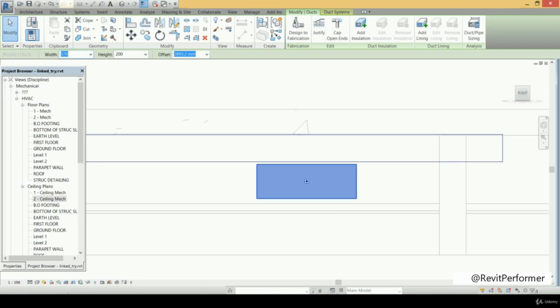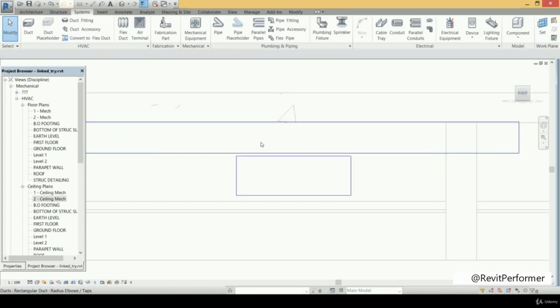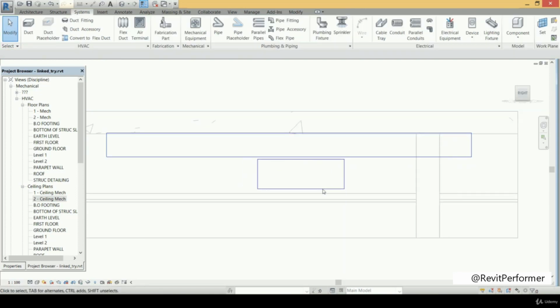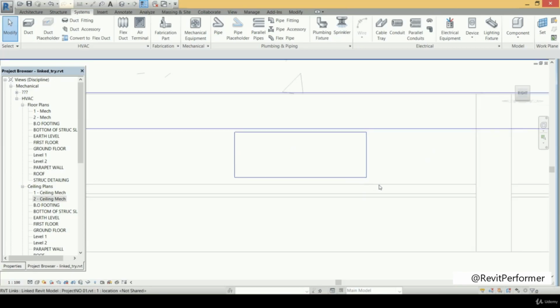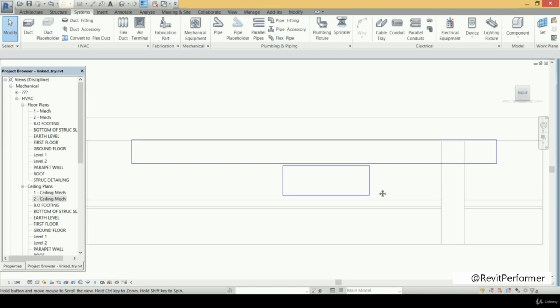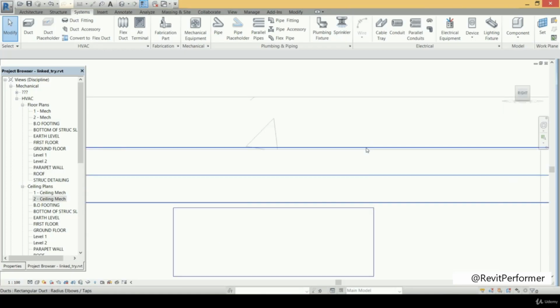So at that condition, we will find that we have the cross-sectional area constant, so the airflow inside it will be a constant value, and at the same time we have decreased the height, so we provide more free distance for the two ducts to be installed at each other. So you can see here, this is the suspended ceiling, this is the upper surface of the suspended ceiling, and this is the upper surface here. This one is the upper surface of the concrete ceiling.